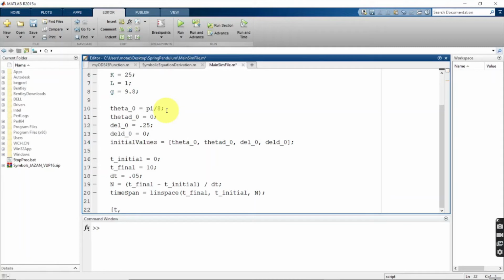Next we're going to run the ODE45. Basically we have a time and a z; it's going to return these two parameters. We call ODE45, and we have to use our function handle at this point with an @ symbol. So we call our function handle, the ODE45 function, comma.